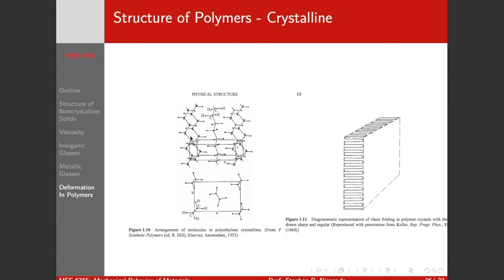This is polyethylene, and we get a unit cell here, right? And remember, we have an inherent anisotropy in our crystal properties because along this direction we're pulling along the carbon-carbon backbone. Along this direction we're pulling on the van der Waals forces that hold these chains in alignment.